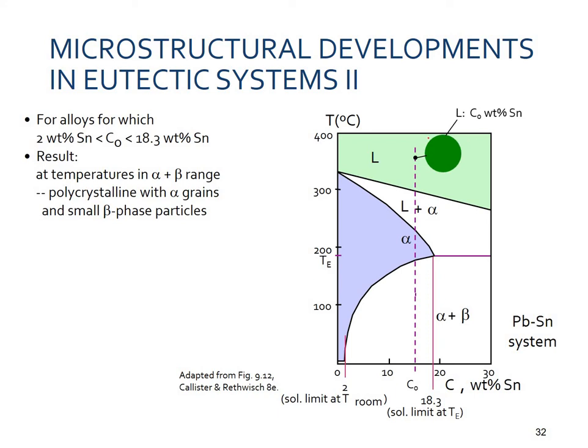We see that here is the liquid region again. So this is the liquid and alpha, the liquid region and the alpha phase going in. Now it is completely transformed into the alpha. But now, on further cooling, we may see some of the beta. These red spots are the beta phases that